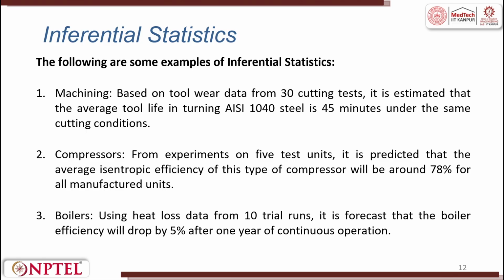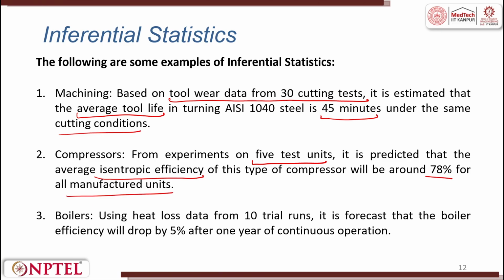In machining, an inferential statement you see: based upon tool wear data from 30 cutting tests, it is estimated that average tool life in turning AISI 1040 steel is 45 minutes under the same cutting conditions. This is an inferential statement. In compressors, for experiments on 5 test units, it is predicted that average isentropic efficiency of this type of compressor will be around 78% for all manufacturing units.